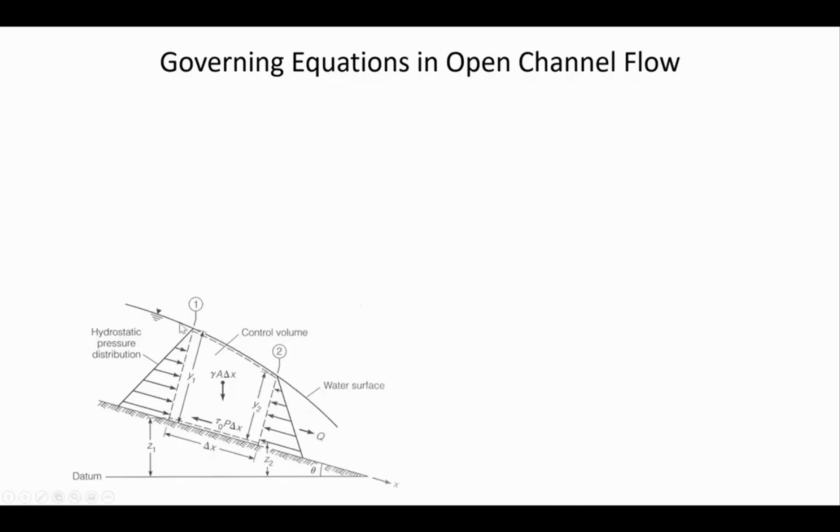So the reason why they show that is just to emphasize the point that this equation can apply whether you have uniform flow or non-uniform flow. The same force balance can be done. And here, the depth of flow is decreasing in the direction of flow. So see how the depth is getting shallower and shallower? So what we're going to do is a force balance, and consider all of the forces that apply to some element of water. So the water inside the dashed lines, let's look at what's happening with that system.